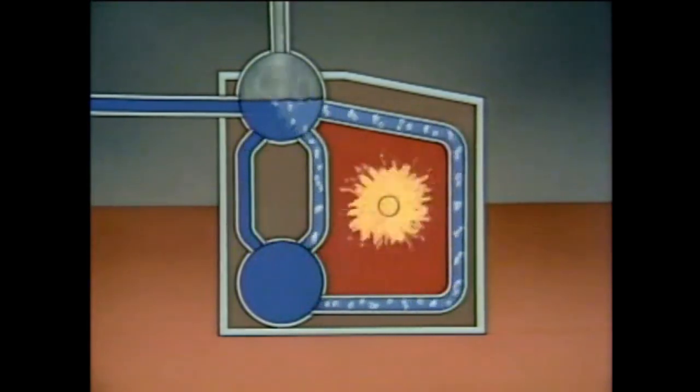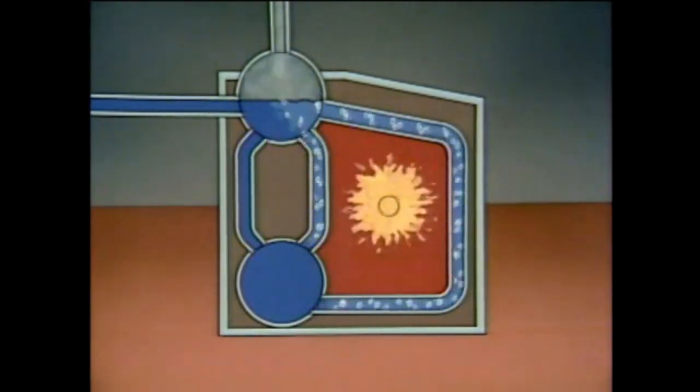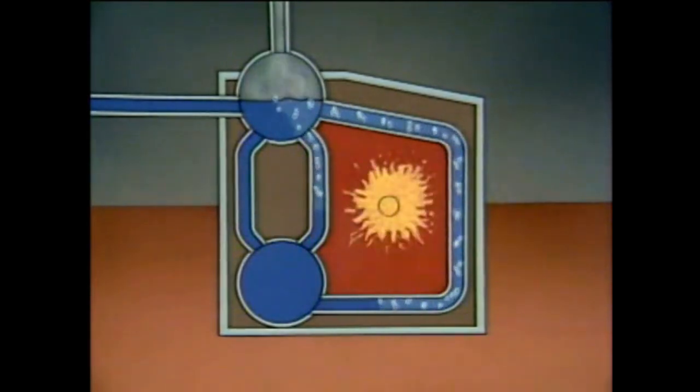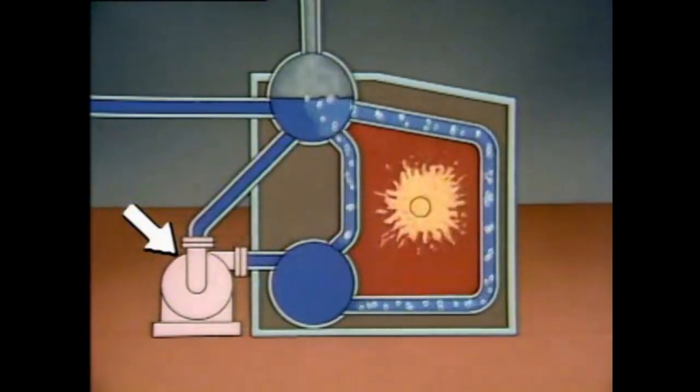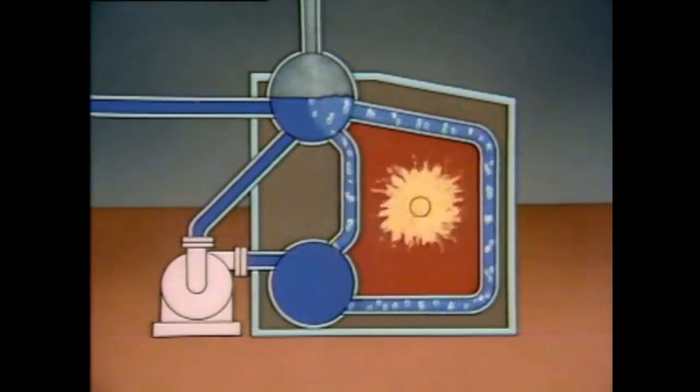The steam flows to the plant through the steam outlet, and the water level is maintained by the water flowing through the feed-water inlet. As long as combustion takes place, natural circulation continues. Not all water tube boilers rely on natural circulation. In some cases, a circulating water pump is used to produce the flow of water in a boiler. This type of circulation is called controlled or forced circulation.